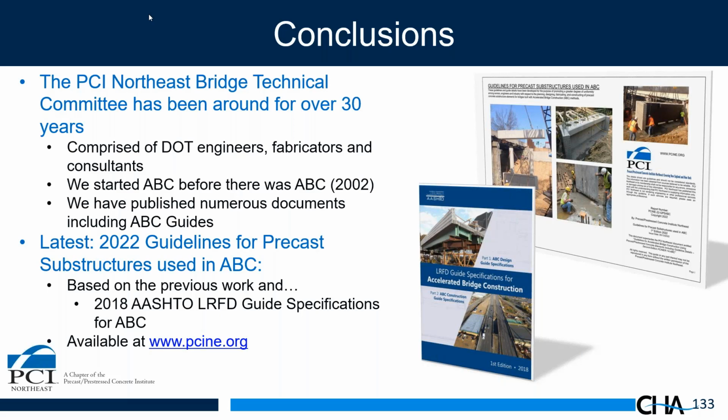Yeah, I saw this question before, and I wasn't sure whether it meant installing it underwater or having it underwater in the final condition. Okay, first half, if it meant installing it underwater, I know of no connection that can be installed underwater. So you have to dewater the connection to make it. As far as exposing it to water afterwards, these connections are truly emulative of cast in place construction.